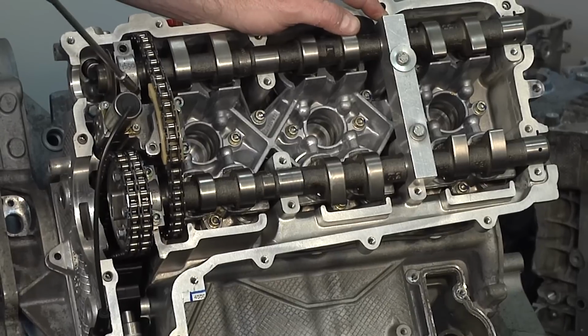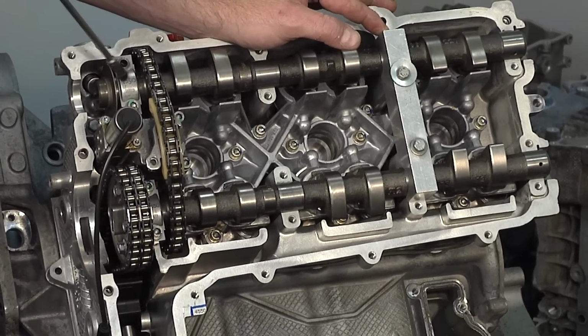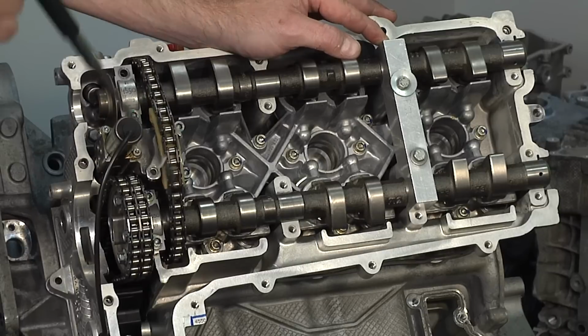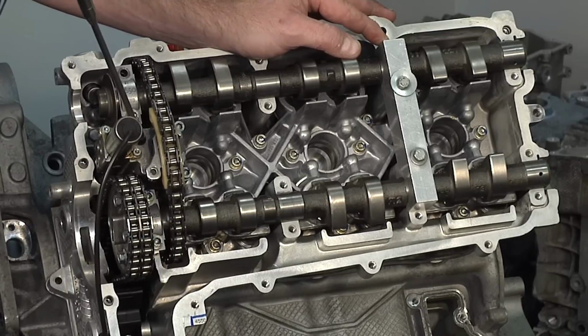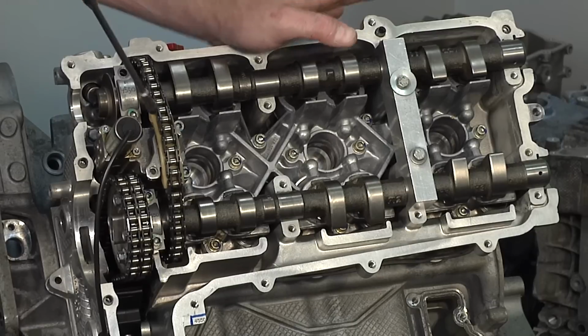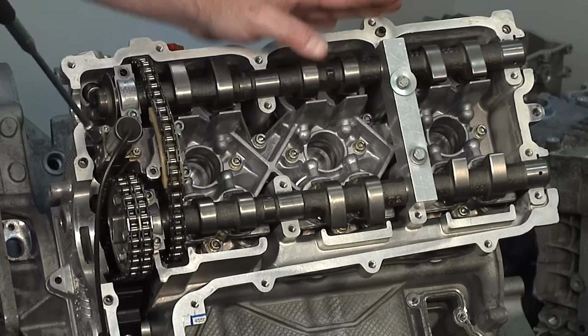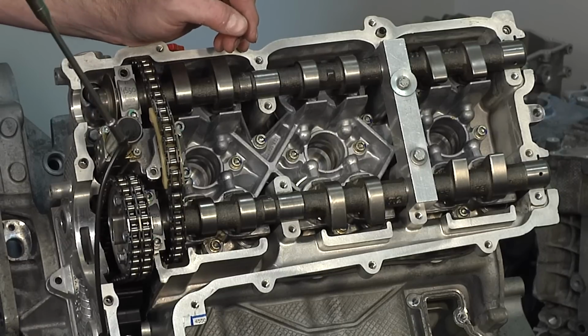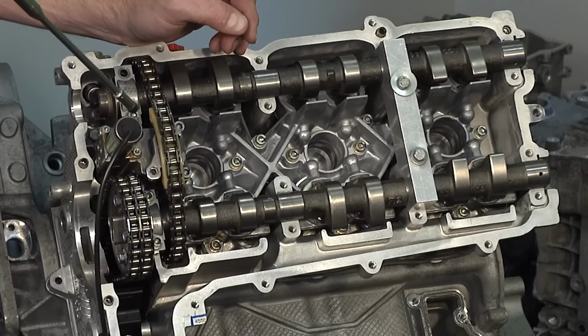You can remove the 5 millimeter Allen head bolts that hold the camshaft cover, or camshaft caps in place on the intake and the exhaust, as well as the 3 bolts that are 5 millimeter Allen head that also hold the chain adjuster in, okay? Now keep in mind, all this stuff is going to be reset when it goes back together again. I've seen people mark a bunch of stuff and do all kinds of things. You don't have to do that right now. There's only one part I'm going to show you a little bit later on that you need to mark for allocation. And that's just going to be when you go to separate these 2 camshafts from the chain adjuster unit. There's 2 markings we're going to put on the chains to simplify that going back together, okay?